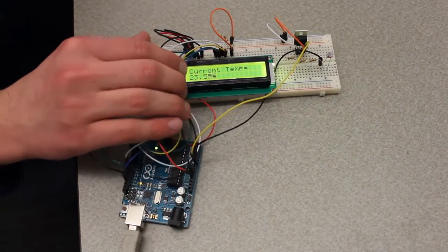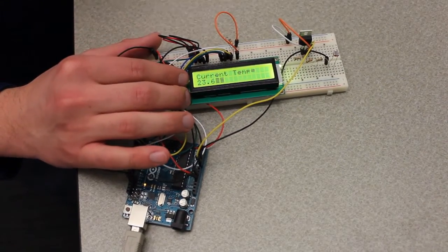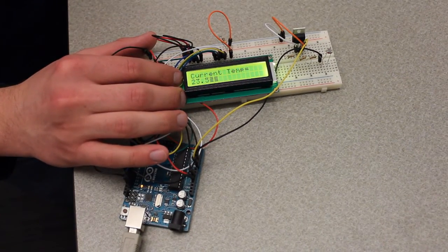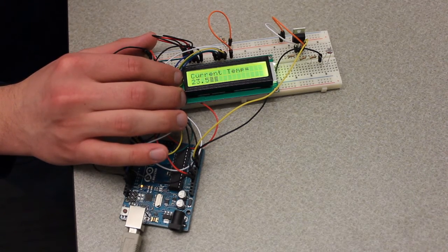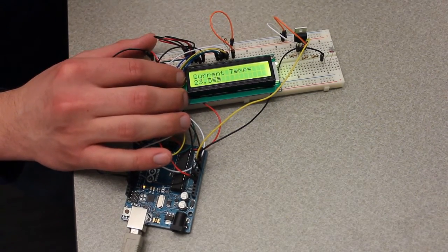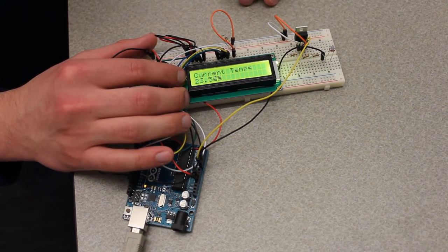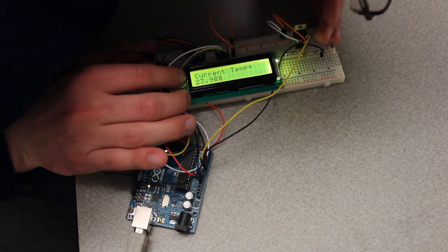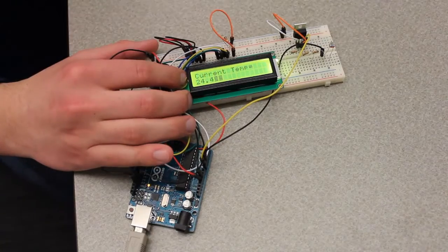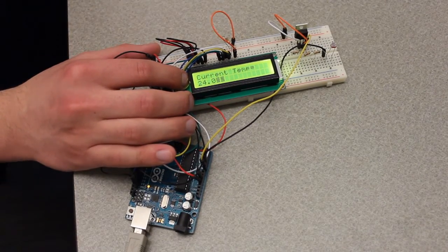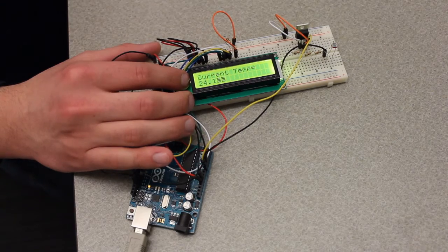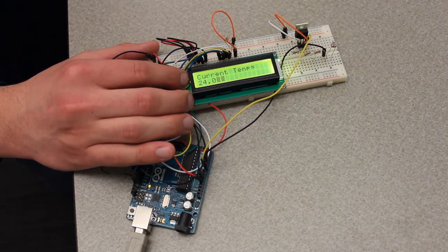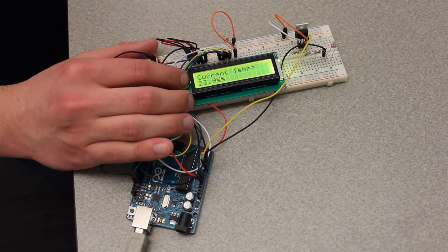So here is the LCD display. If I move the wires, hopefully you can see it says current temp equals. As you can see, it's fluctuating slightly, and that's because the temperature in the room is hopefully fairly constant. But if I move in and breathe on the transistor, hopefully it'll heat up a little bit. So you can see it went from 23 up all the way to 24.5, and so again, it's not the most accurate way to measure temperature, but it is a fairly good way given the tools we have.